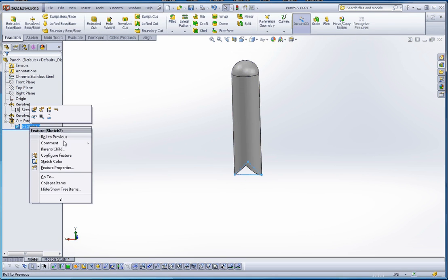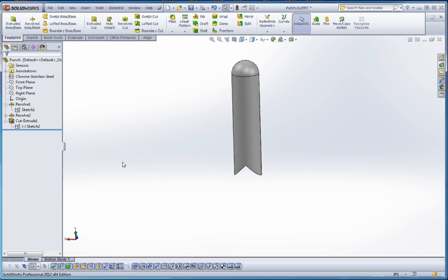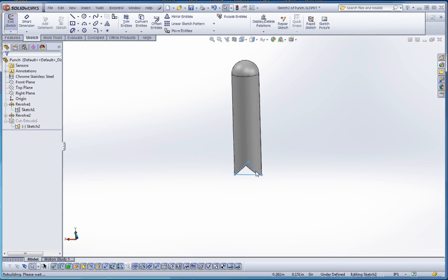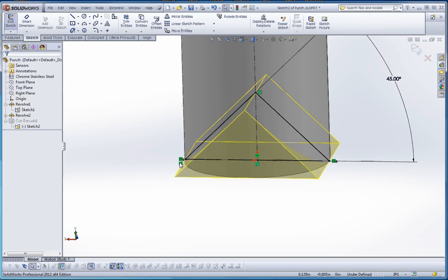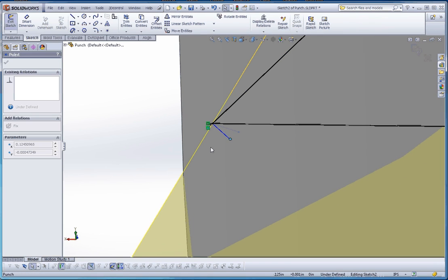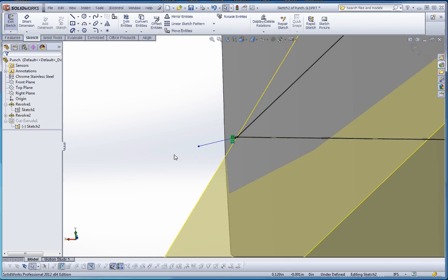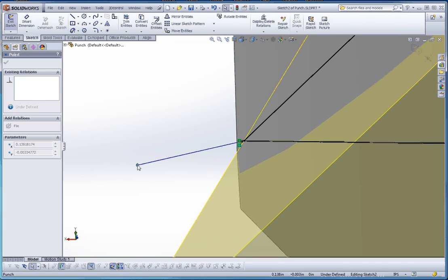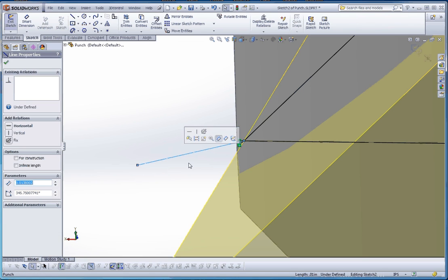Let's right click and go to what's wrong. Oh, that's not there either. Oh, let's see something down here. Oh, you got yourself a pony line. It didn't really affect the model at all, but here's a little line that, when you're clicking a little bit too fast, it kind of puts in these little pony lines. Sometimes they're hard to see.